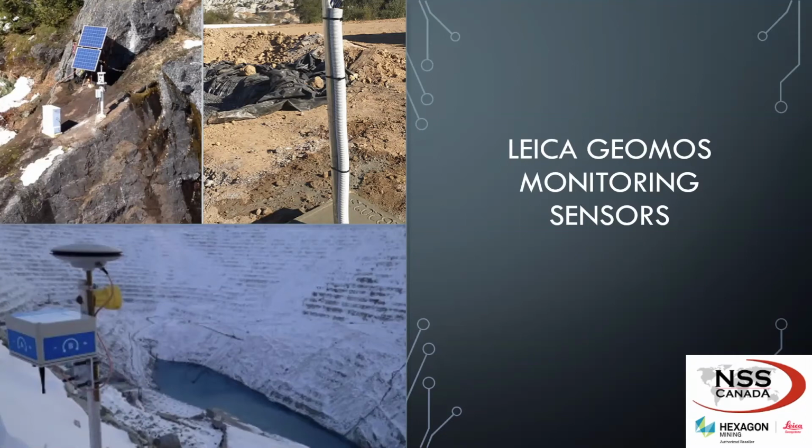We have the piezometer sensors, which monitor the pressure depth of groundwater that helps Leica GeoMoS Monitor distinguish false ground movements. Leica GNSS antennas, GPS, can provide added real-time analysis capabilities and improve status information with multiple sensor monitoring stations.